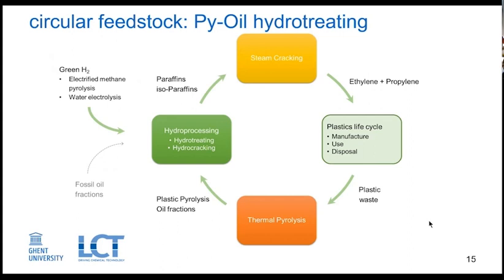Indeed, in virgin fractions there are no olefins at all, but in some cracked heavy fractions coming from delayed coker, for instance, there could be some olefins. But in plastic pyrolysis oil the amount could range even to 50%, with a lot of olefins that are very unstable.